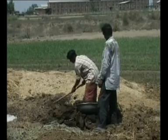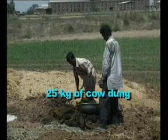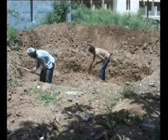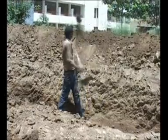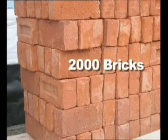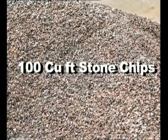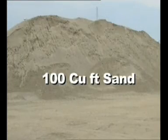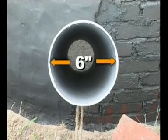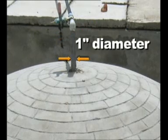For producing 1 cubic meter of biogas, 25 kilograms of cow dung and 25 liters of water are required every day. For the construction of a 4 cubic meter capacity biogas plant, the materials required are 2000 bricks, 18 bags of cement, 100 cubic feet stone chips, 100 cubic feet sand, a 6 feet long pipe having 6-inch diameter, and a 1.5 feet gas outlet pipe of 1-inch diameter.